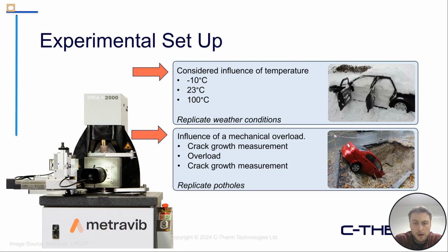100 seems really high in terms of what we see in the environment, but due to the heat buildup that a tire will see during operation, 100 degrees Celsius could be happening in your tire due to the poor thermal conductivity of the material, as well as the heat generation due to the internal friction of the rubber material as it's deforming.